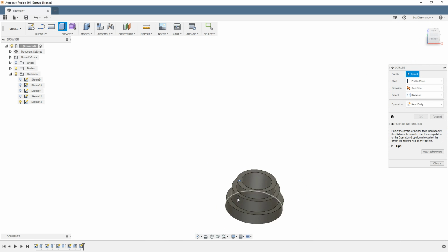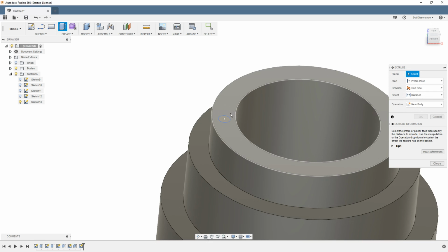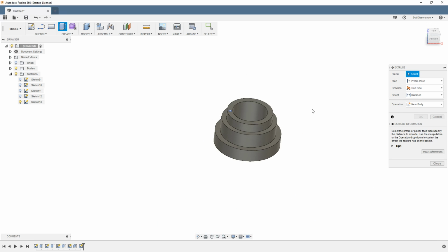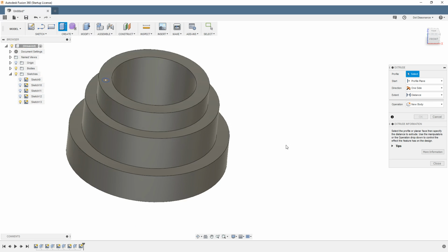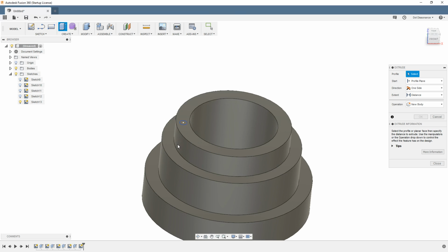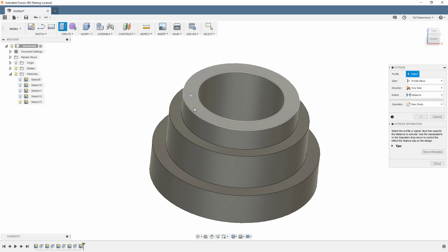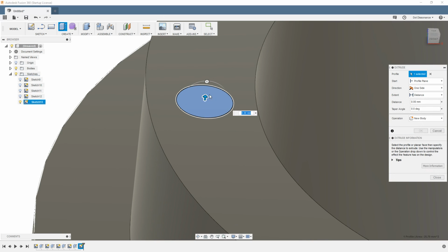Don't try to select something way out here. People that are doing that, I've found, do this because they are not comfortable with the zoom. It zooms wherever your mouse is. So if my mouse is over here, it's going to make this area that I'm picking on center. If it's over here, I'm going to go into that area. So get used to it and hold down Control, pan, get super comfortable. Zoom in, get a hold of that because you don't want to get anything else.